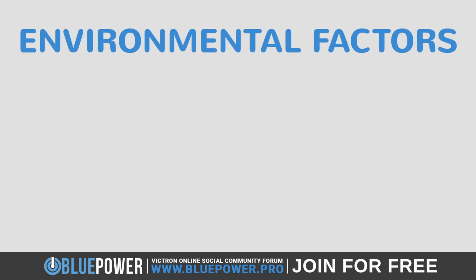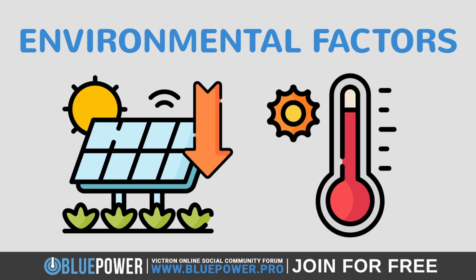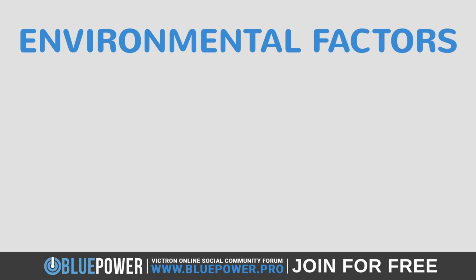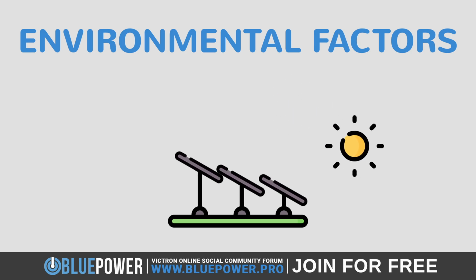Since solar cells are exposed to the outdoors, environmental factors must be considered. Solar cell efficiency typically decreases with an increase in temperature. This is due to the increase in intrinsic carrier concentration in the semiconductor material, which leads to higher recombination rates. The intensity and spectrum of sunlight also affect efficiency. Solar cells perform differently under varying light conditions. Then, the angle at which sunlight strikes the solar panel impacts the amount of light absorbed. For this reason, specialized solar trackers can optimize this angle throughout the day.